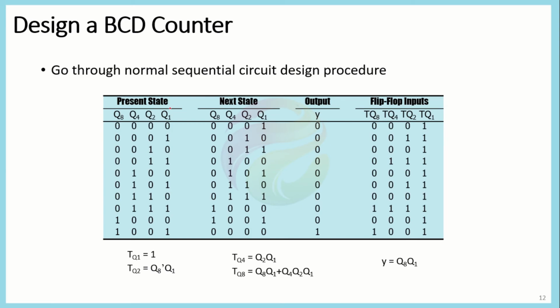We would first represent that system in the form of a diagram, or in the form of a state table. If we represent it in the form of a state table, we could easily define the inputs of each of the flip-flops that are involved in it. If we are using the T flip-flop, then we could accurately define what kind of pattern each of them should follow. And for each of them, the input is represented in the form of a single bit,